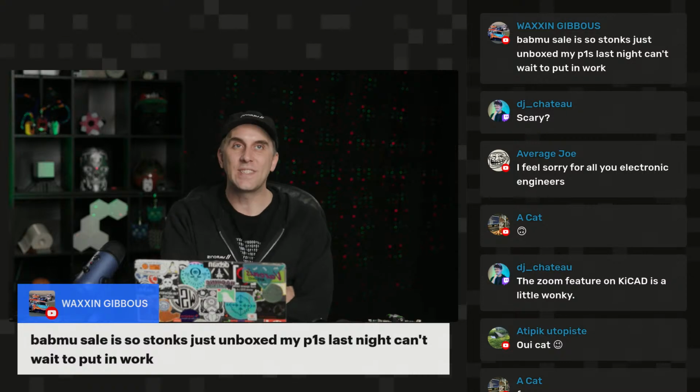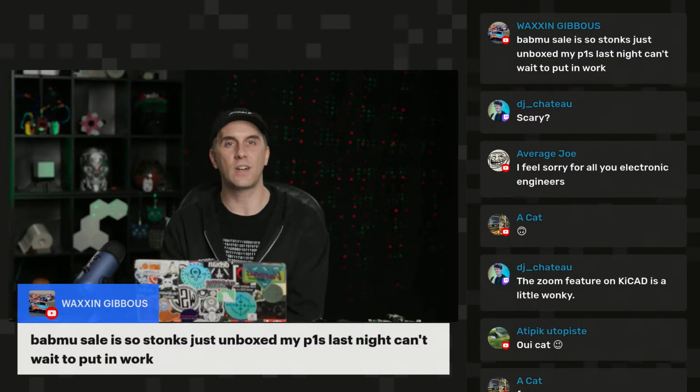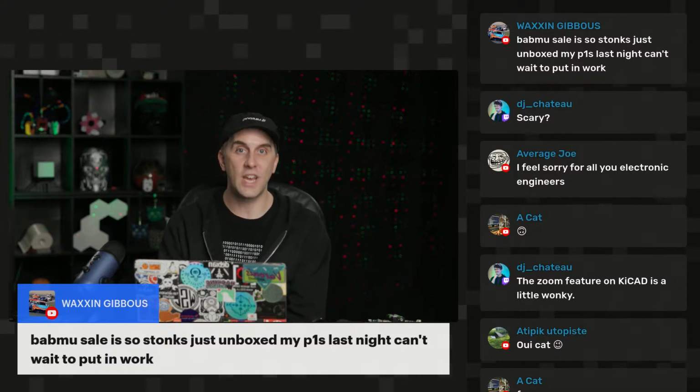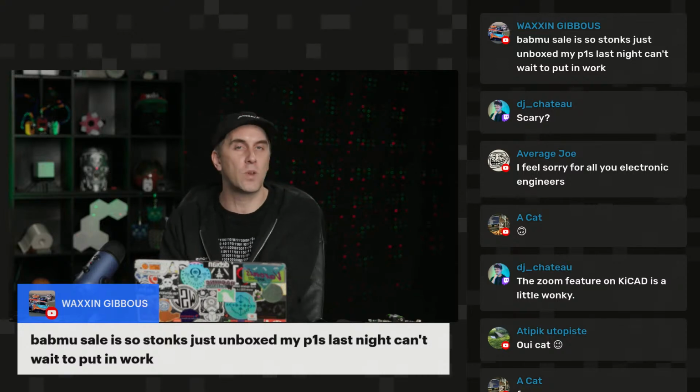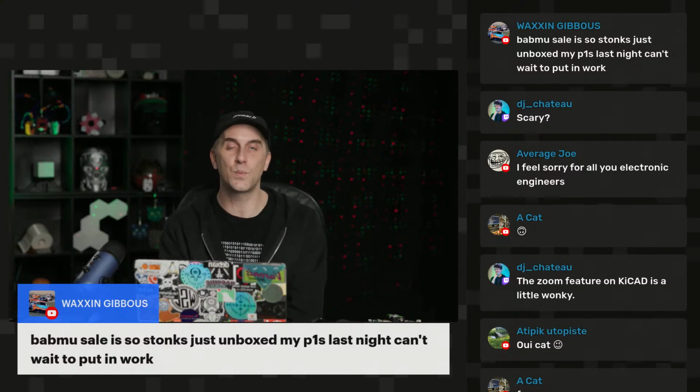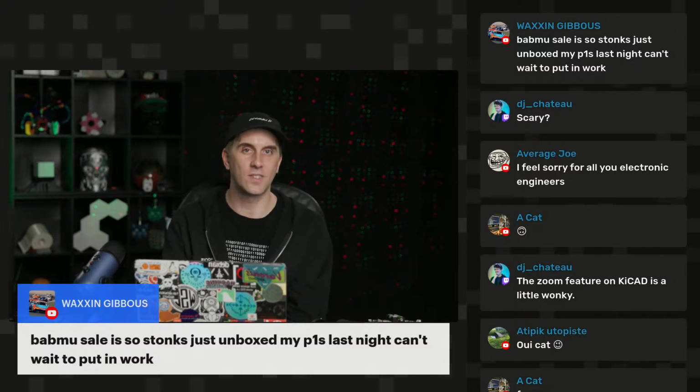But once I put in the proper material settings for the glow filament, it started to feed a little bit better and I had less trouble with it. But I've definitely been servicing my Bamboo printers. They do jam, they do clog, there are problems. My P1S upstairs is currently jammed because the filament broke off inside, and I have to figure out how to remove it, which is a different process from what I'm used to. So there definitely are problems. It is not a flawless system, but it is pretty impressive, and when it's working properly, it really returns some excellent results. So there's lots of applications to these kinds of multi-material prints.